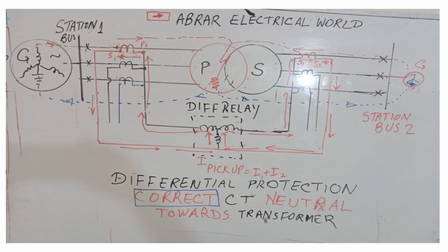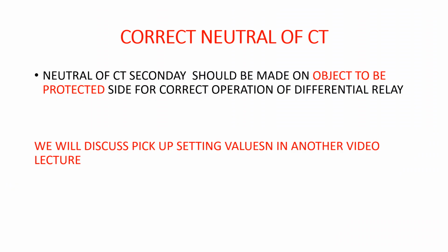So I hope you liked this lecture, and I'm sure that you have understood the basic concept that the neutral of the CT secondary should be made on the object to be protected side for correct operation of the differential relay. We will discuss pickup setting values in another video lecture.